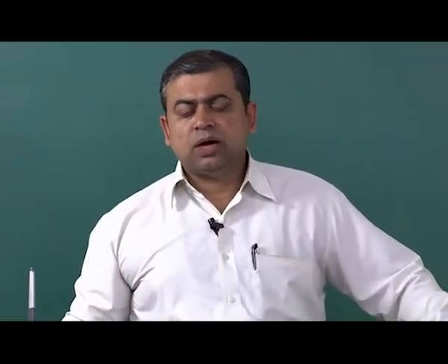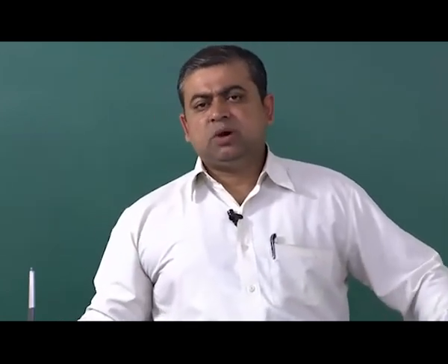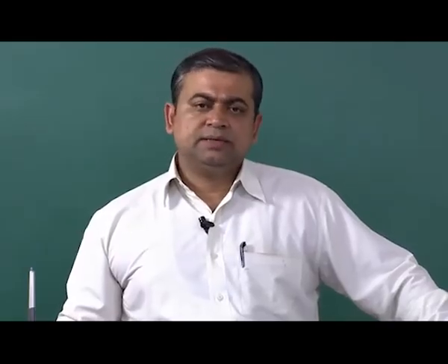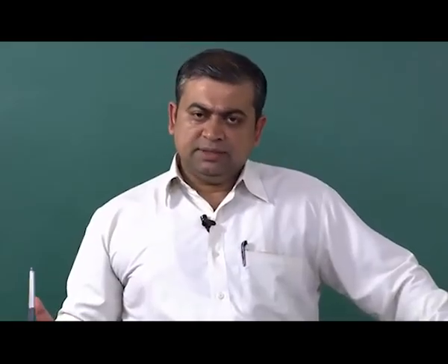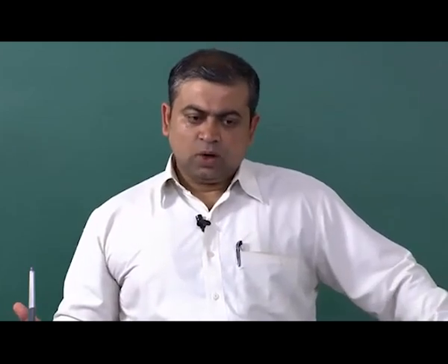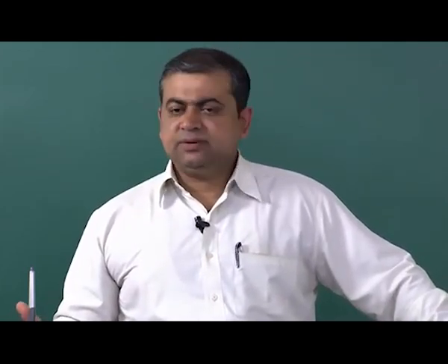We exclusively discussed how the beam can be rastered on a surface and how it is a high resolution process of writing because of the extremely small wavelength and limited diffraction which would happen to the beam. And then we talked about certain modalities of the machining parameters and how the beam process can be modeled in terms of the requirement of power and the other parameters of a beam, like the diameter, the velocity of raster of the beam, the workpiece material properties like thermal conductivity, and so on and so forth.